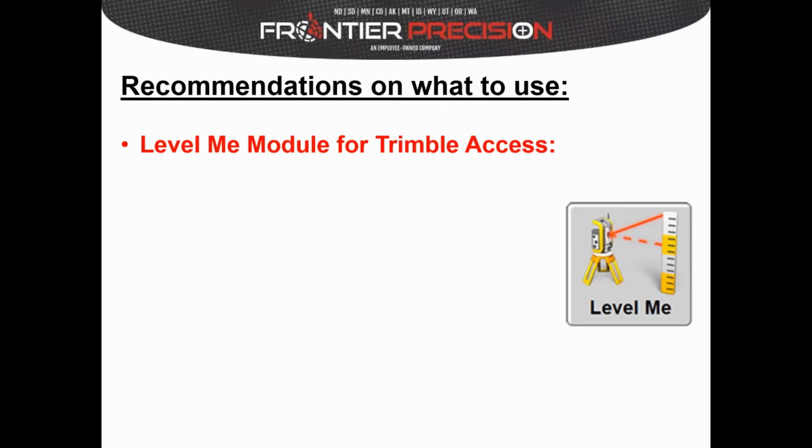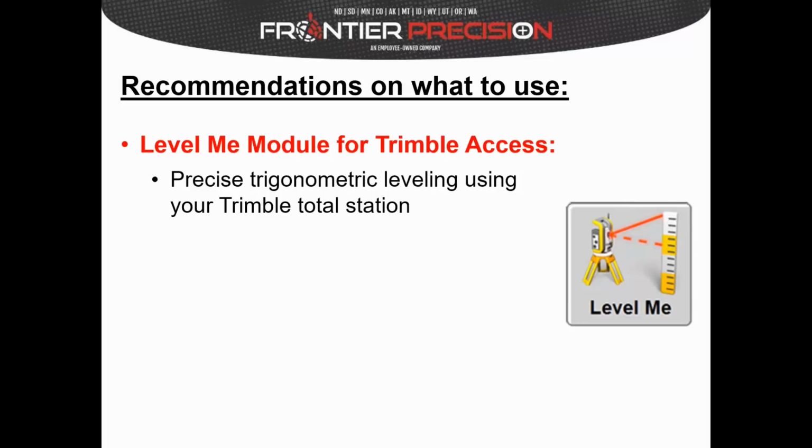Another thing I want to throw in here, though, if you're looking for some ability to get very precise elevation information on your points, but don't want to pull out a level, maybe just still using your total station, we would recommend the Level Me module for access. I know some of you on this webinar, just looking at the names, are using this already. What it does is it allows you to basically use your total station to do some very precise trigonometric leveling,